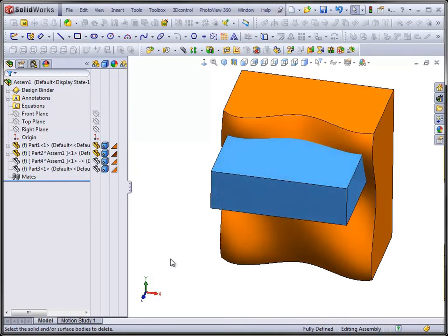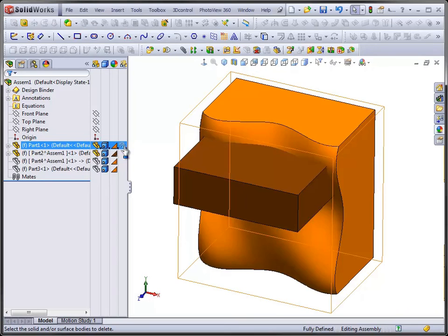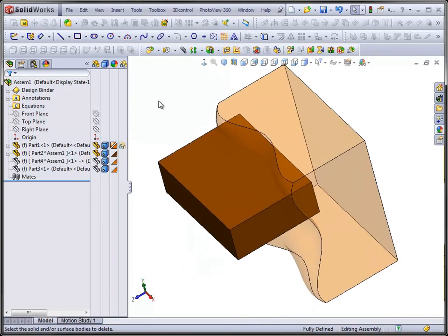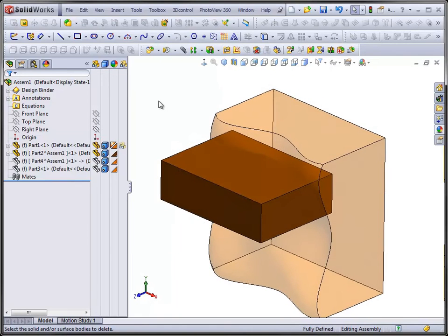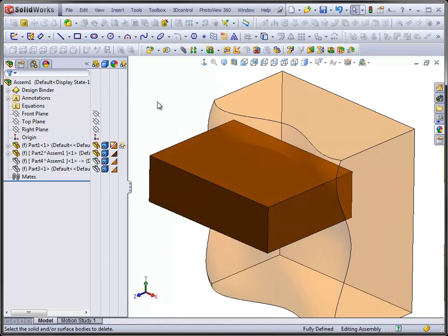Hide those away, and here I have a shape that is quite shapely. Here I have a plate overlapping that shape, and I'll set the shape transparent so we can see that that plate is presently longer than it should be. So we wish to trim that. Now another way to subtract one part from another part is another command called insert indent. Insert feature indent using the cut option. It's basically the exact same thing as the cavity command.